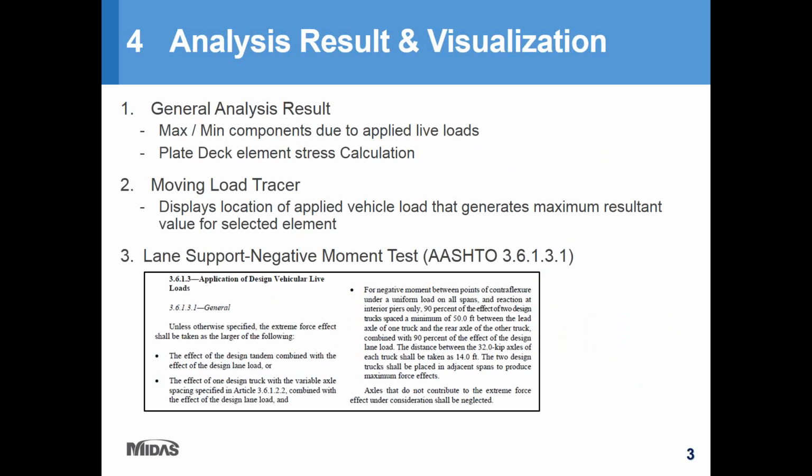Analysis results can be retrieved in tabular format, as with our other analysis results. When the deck was modeled with plate elements, stress calculation for plate elements is also available. Moving load tracer displays the location of the applied vehicle under the worst case scenario of the applied loads.